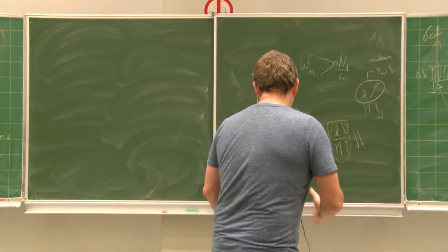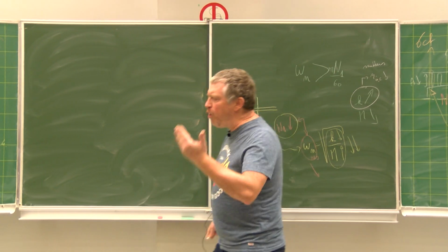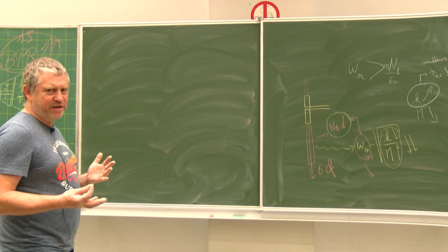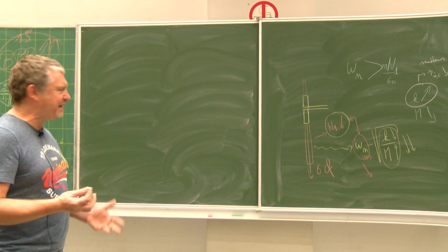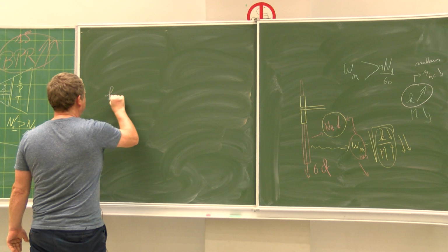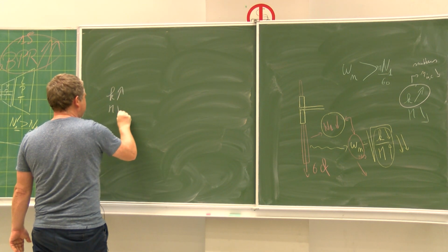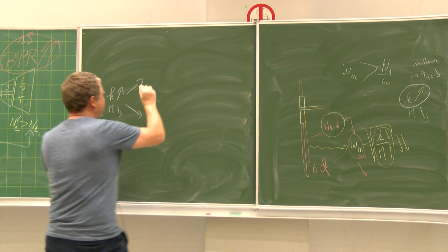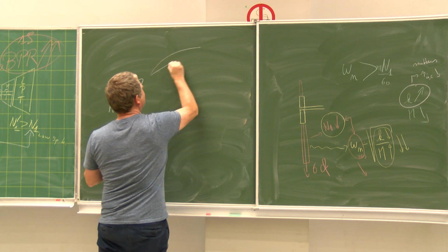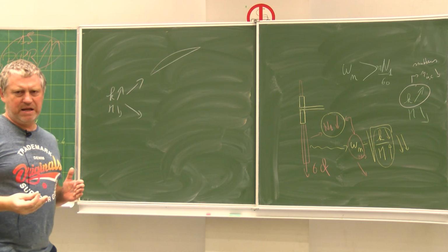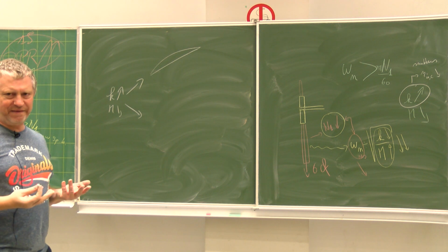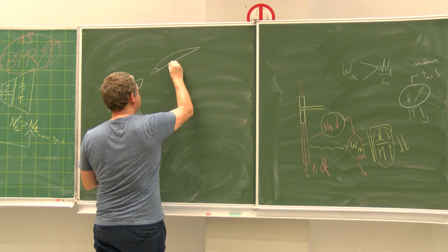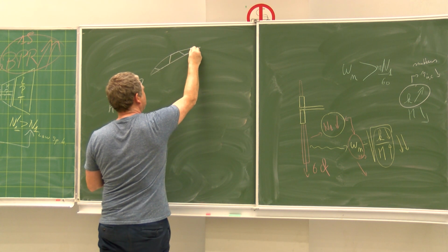And after this, let's say, small improvement, a small solution, the big players, the big companies, have invented two technologies in order to increase K and to decrease M. There are two technologies available on the market. The first one is to build a blade that is, let's say, empty. This is what is called hollow fan blades. So the blade is empty with just a stiffener that is something like this.